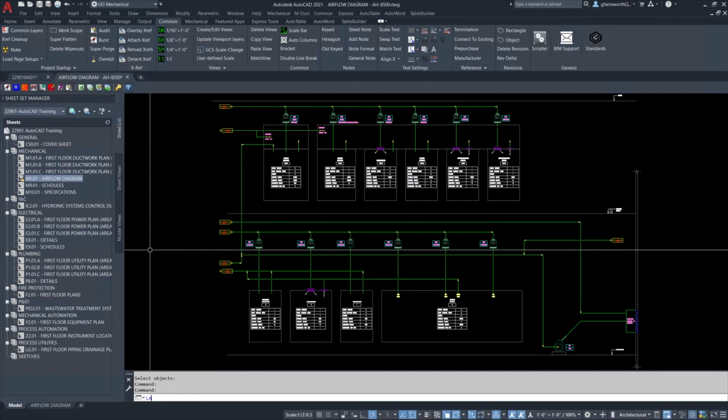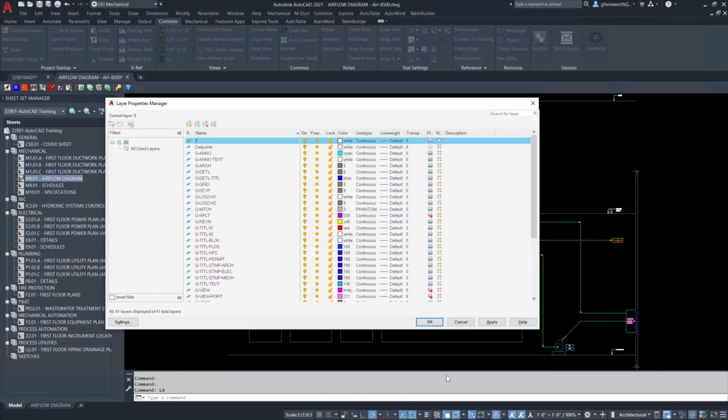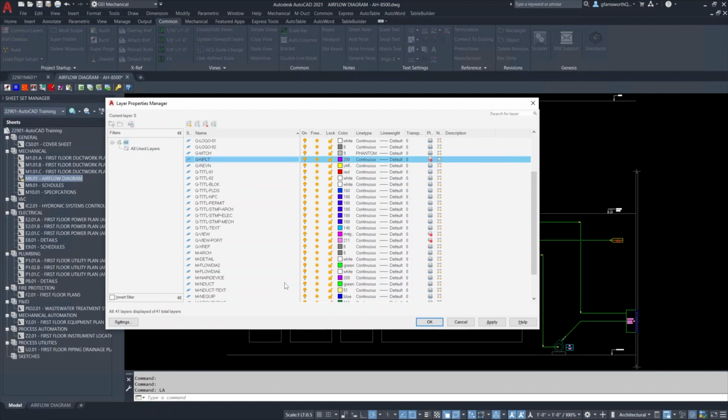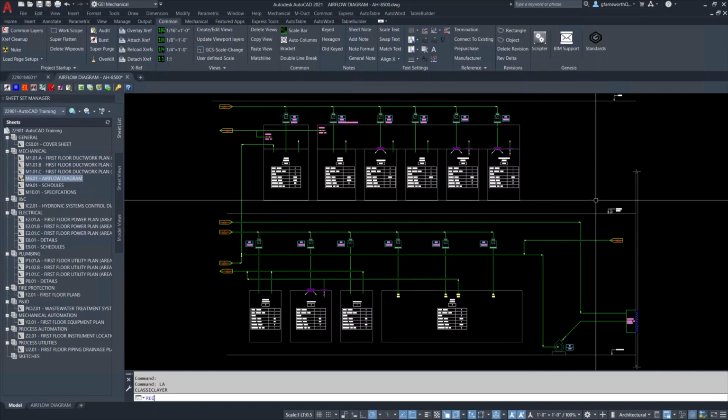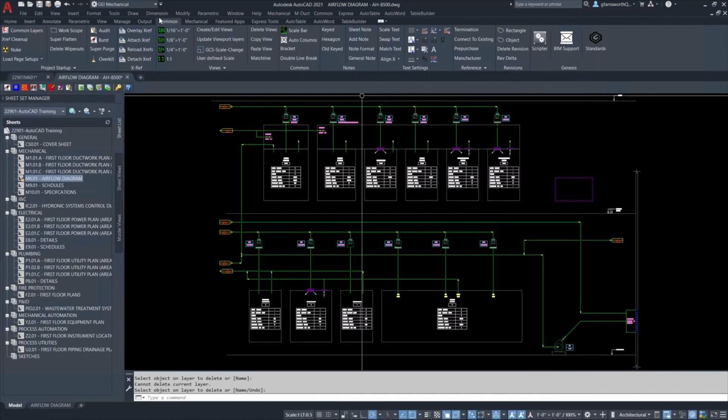Lastly, you want to think about layers. Each layer in an AutoCAD file you link to will appear as a visibility parameter in imported categories. Earlier, we purged to make sure that only the used layers will be linked to Revit. But there's more to think about. For instance, Revit doesn't understand non-plotting layers. Revit will plot them. So if you have items on a non-plotting layer, you want to manage them in AutoCAD before you link the file into Revit.